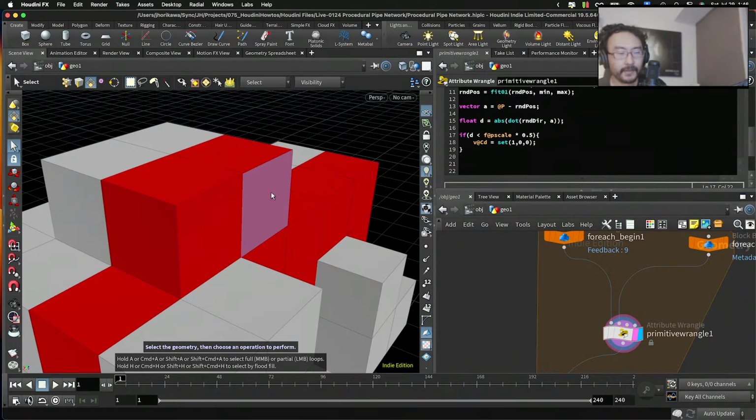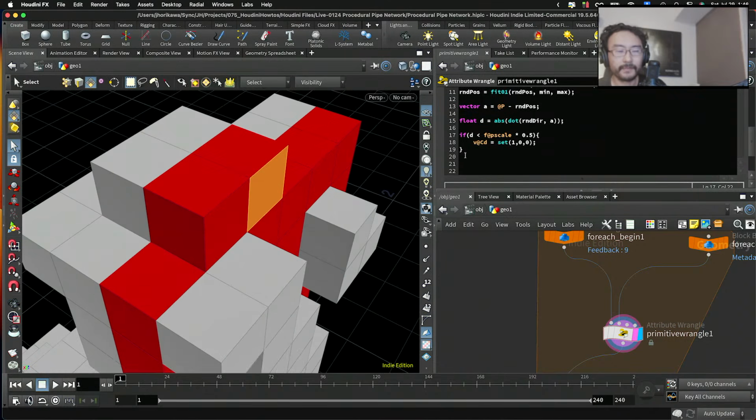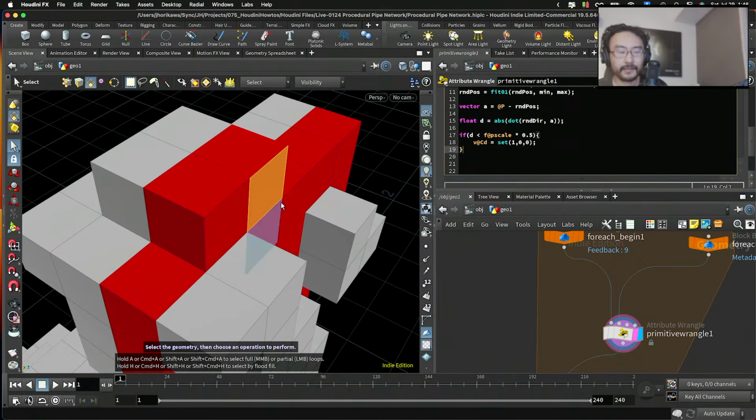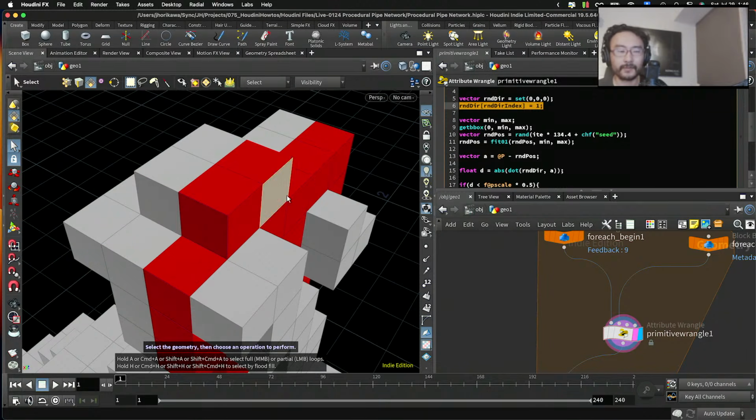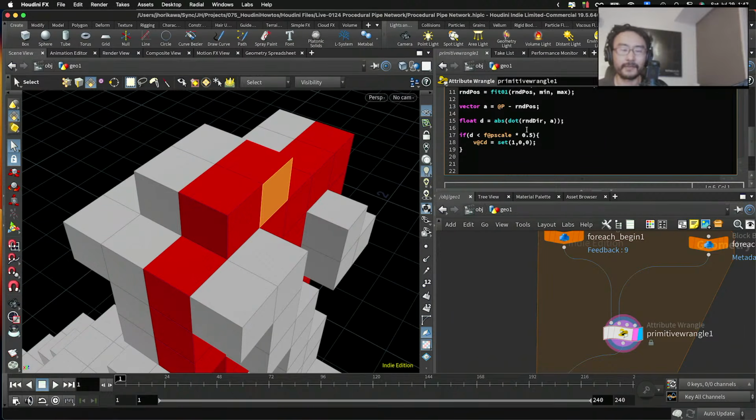If I think about this point, so if this is the point position, okay. So maybe I also need to consider whether this direction is perpendicular, is equal to the direction which I've defined here. So if the dot product between the normal of this face and this direction is equal to 1 or equal to -1, then I shouldn't include that as a strip.